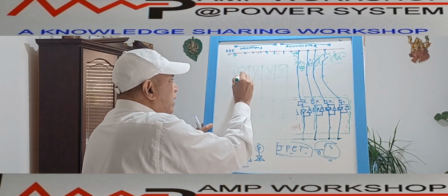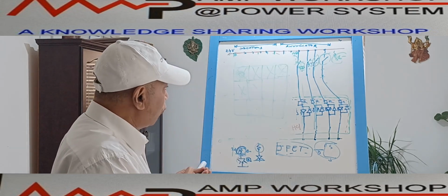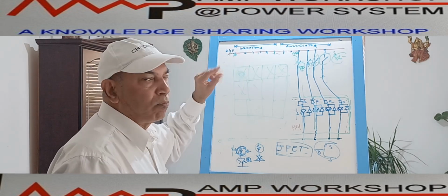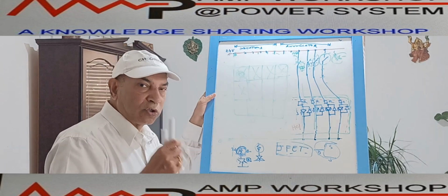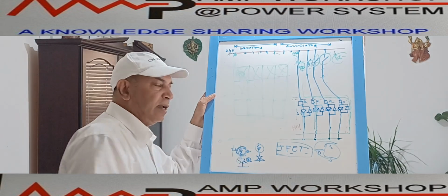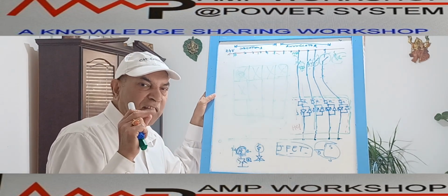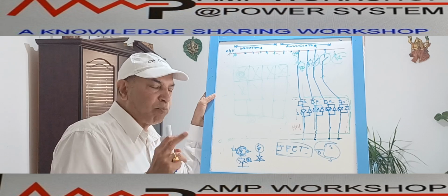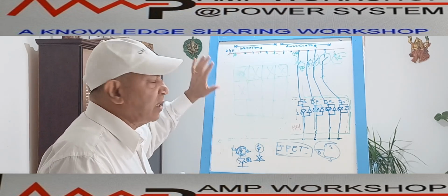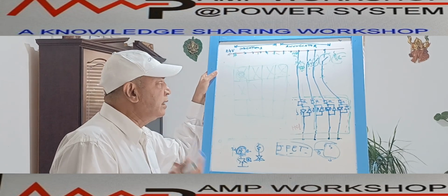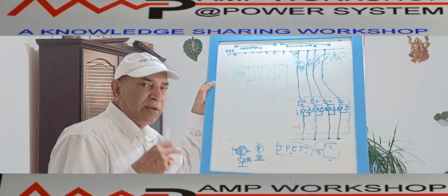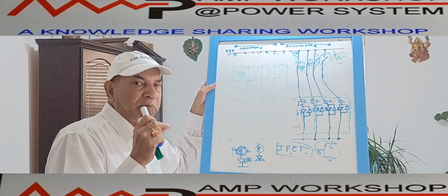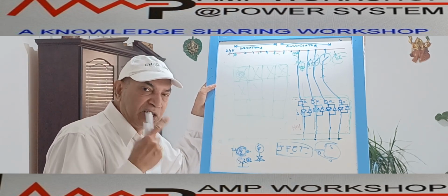So there is a lamp over here and there is a horn output. When any of the functions operate, we can see from here that this light is glowing. Nowadays in most modern annunciators, we can flash the lamp in various ways, as well as make it steady on or off. We can program this annunciator that way. In the digital annunciator, the indication lamp can be steady, or it could flash, and in flashing we can make high speed flash or low speed flash. All this we can program in the digital annunciator.